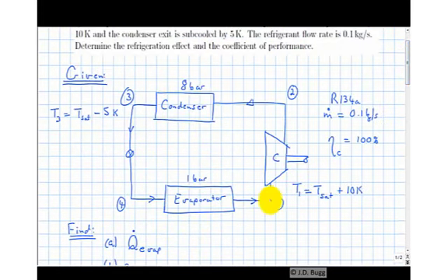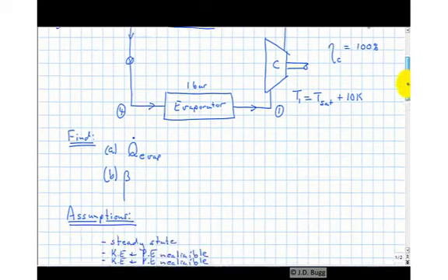The inlet conditions we know. We already used those for the evaporator. We also know this compressor has an isentropic efficiency of 100%. And we know the discharge pressure is at 8 bar. So this is a pretty standard calculation for this compressor. We're going to have to figure out an extra property at the exit, but because it is isentropic, that's the entropy. So we can take the entropy at 1, it will be the same at 2. So then we have our two properties at the exit, entropy and pressure. So we can get exit enthalpy. So that's what we're going to do.